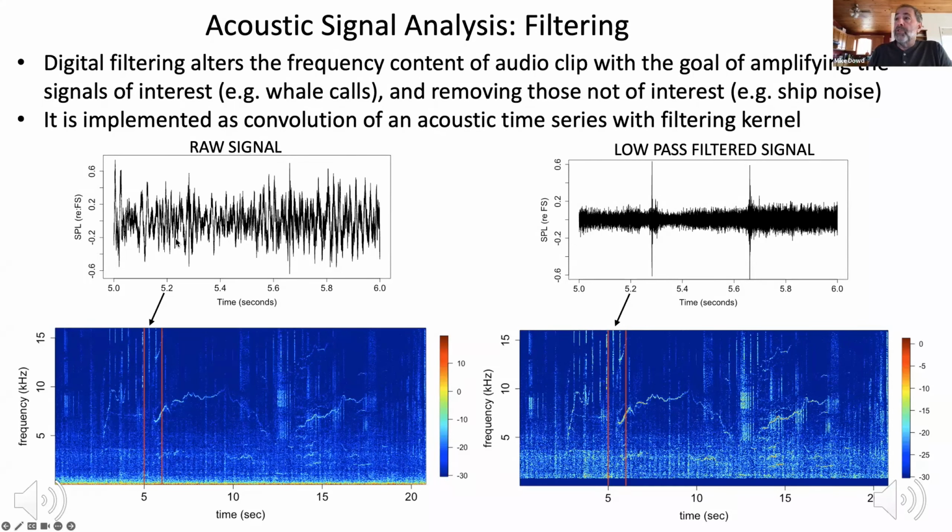So here, for example, is a raw signal I took from some hydrophone that Ruth gave me. This is a 1 second clip. It corresponds to this area of the spectrogram. You can actually see the oscillations right here. These oscillations are 60 hertz oscillations, and they're associated with a ship passing by. That's the frequency of the crankshaft turning in the ship and the direct drive, so that's the propeller rotation frequency as well. 60 hertz sitting there.